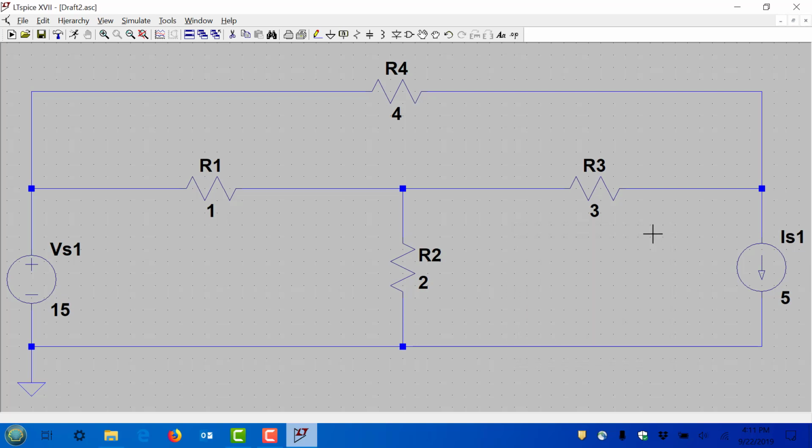Okay, great. So anyway, what I just showed you, you don't need, because in fact we are ready to simulate. We were ready to simulate maybe 5 minutes ago already, but this is ready to simulate now. The only thing it's missing is the type of simulation. There are different kinds of simulations we can do. Now, for us, we're going to do what's called DC analysis, or what's also called operating point analysis. What is that? This is where we calculate all constant or DC voltages and currents for all the elements. It's basically what we've done on the homework. That's called DC analysis, or sometimes operating point analysis.